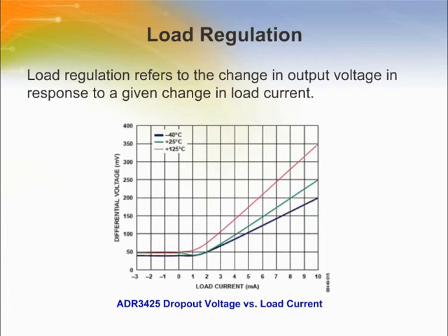It accounts for the effects of self-heating. In general, load regulation deteriorates inversely with the rate at which the load current changes. Output capacitors are recommended to stabilize the output voltage in applications subject to low current transients.